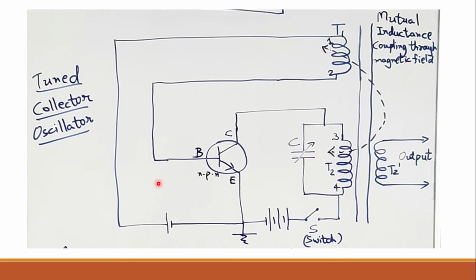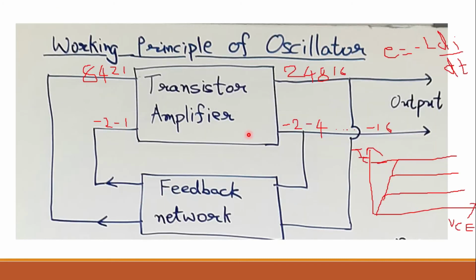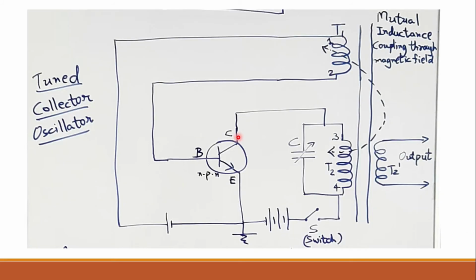So now what will happen, that collector current has increased, so again base current will increase, right? Base current has increased, and that increased base current is coming over here, and again the collector current will increase. So again more flux will be linked, and again the base current will increase, and this cycle will continue up till which point? Up till the transistor gains, or up till the collector current becomes constant or saturated, as we have shown here, up till the point where this collector current becomes saturated, right? So once this collector current becomes saturated, what will happen? That IC will be equal to constant, right?